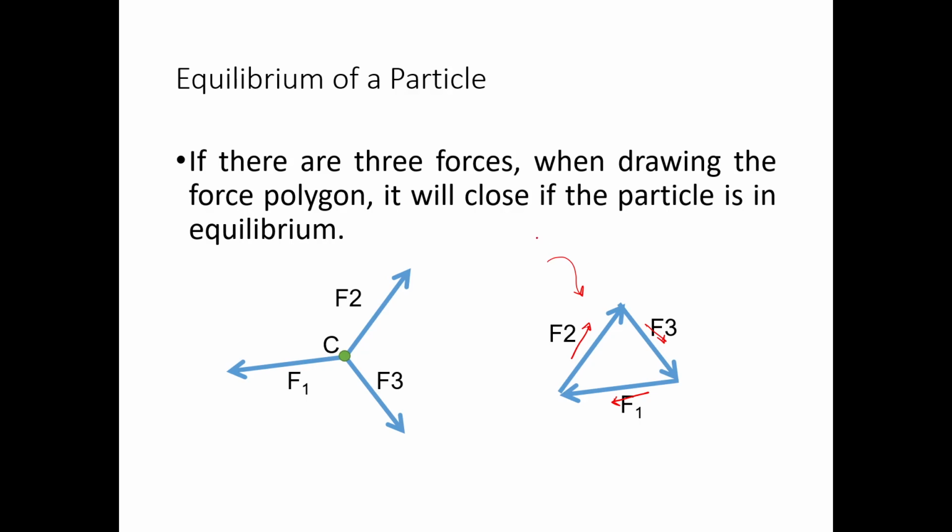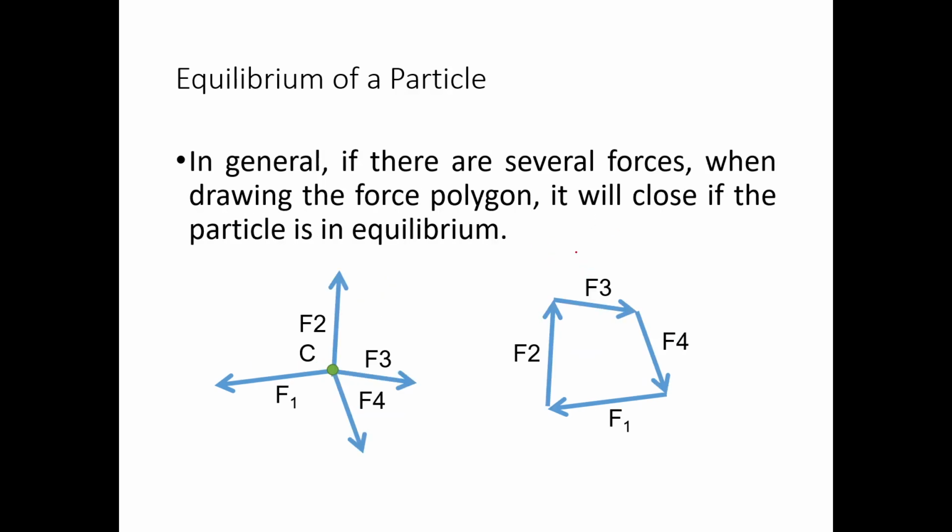There's no resultant force. If you have multiple forces greater than 3, it will still create a closed polygon. A closed polygon will give you an equilibrium force system. Again, notice that there's no resultant force included in your force polygon, only the component forces.